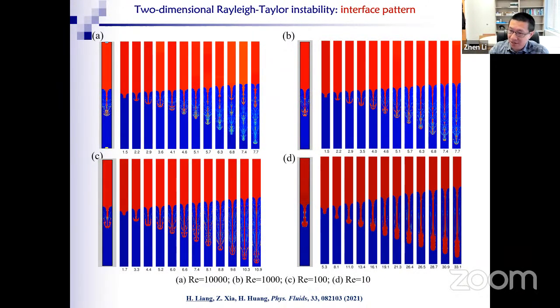Yeah, the Reynolds number in this case is pretty high. No, we have not used turbulence models. This is direct numerical simulation, DNS. So you do not use turbulence models. Okay. So you use a very small mesh size to capture all the details of the small-scale flow, right?